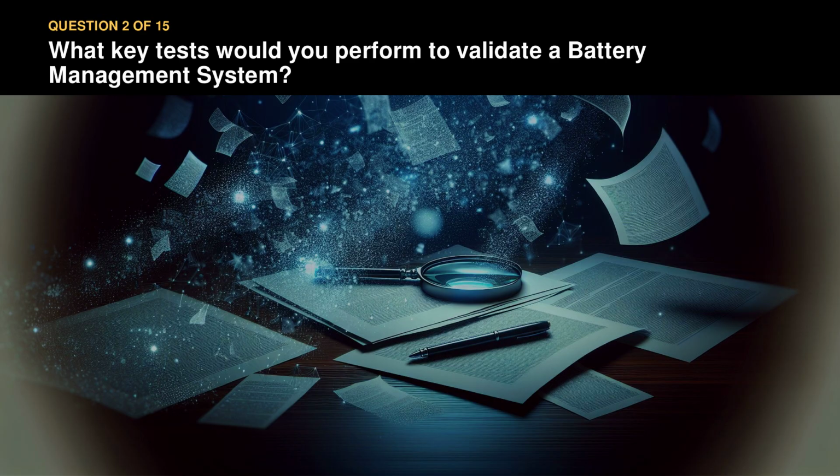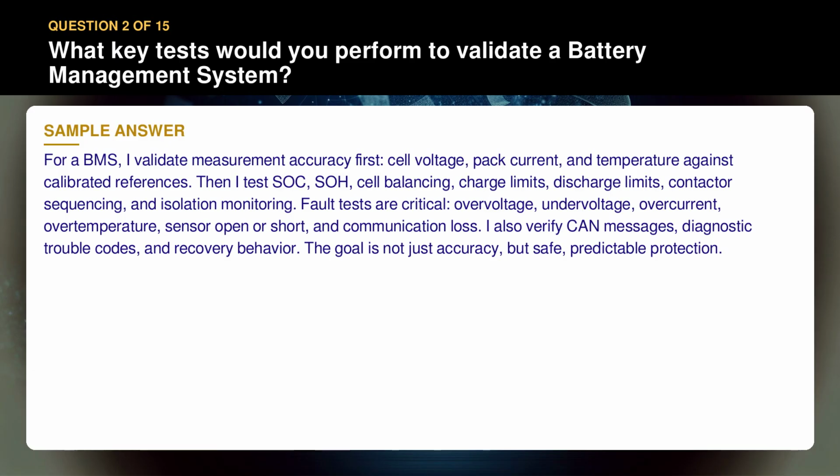Question 2. What key tests would you perform to validate a battery management system? For a BMS, I validate measurement accuracy first: cell voltage, pack current, and temperature against calibrated references. Then, I test SOC, SOH, cell balancing, charge limits, discharge limits, contactor sequencing, and isolation monitoring.